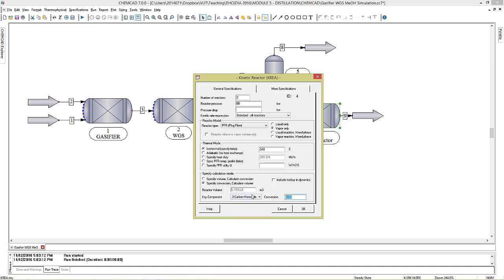If you end up with 2000 cubic meters, maybe it does not make sense, because 2000 cubic meters is such a huge reactor depending on what volumes you are handling. So always keep note that for the conversion that you are getting, your reactor size does make sense. If it does not make sense, go back and check if your rate constants, all the kinetic parameters are calculated correctly. This is where most of us make mistakes. Even if you look at my calculation, you may find that there is a slight mistake here. I may have not calculated this properly.